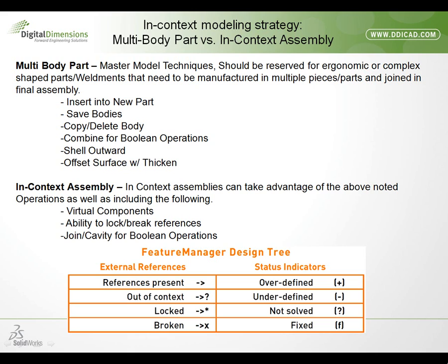If you have that greater than symbol there with a question mark after it, it means that the assembly that contains the context or the other parts that this current part is related to would be currently closed. That is to say, the part may or may not be accurate, but to find out, you need to open the assembly where the context was generated or where that relationship exists.